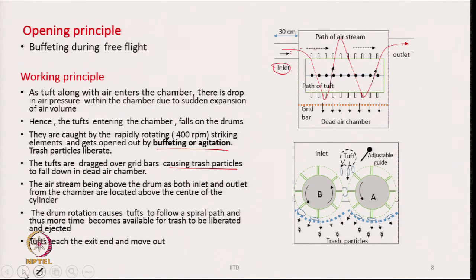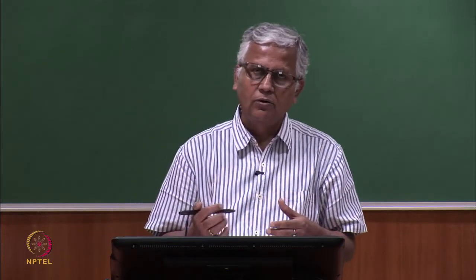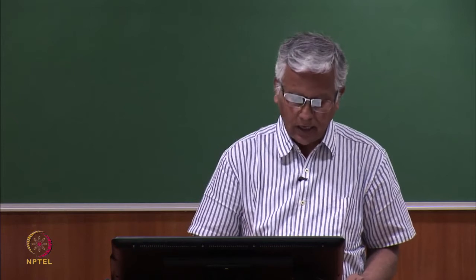And by the time the tufts reach the other end, it will move out. So, this is how the machine is working, because the tufts are acted upon by the striking elements when they are in free flight, and hence the opening capability of the machine is much less, whereas the cleaning action is very high.